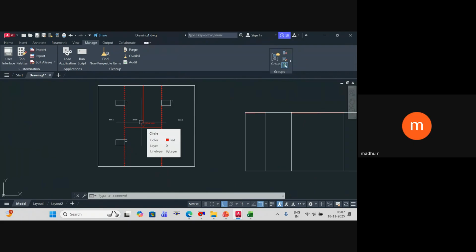But now it is only three zones we have made. In the worst case, if there's a fire in zone B and it has not spread to zone A or zone C, both the sprinklers operate. If you have multiple zones, like 10 zones, how does this work? I've never seen any project with 10 zones. That's way too huge. But in that case also you should take the total flow rate. Probably you'll split it into multiple tanks and have multiple deluge valves. But everything will be operated anyway at the end of the day, isn't it?